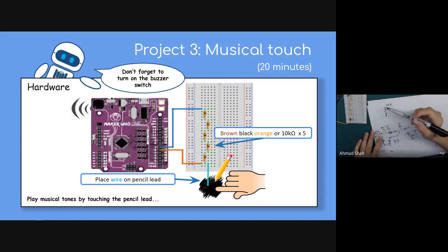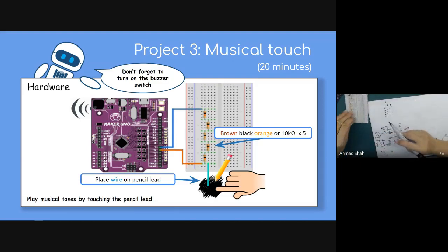If we are looking at only one, the A B C D E are all connected. It's like a wire connected. You are able to plug in another component or another resistor on this same number but different alphabet.